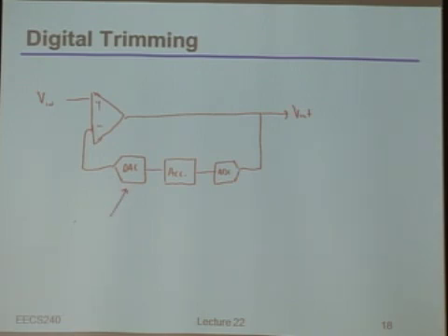So in other words, the LSB or the step size is set by whatever your offset budget is. Because as we'll see in one second, or as perhaps should be obvious, if that DAC has finite resolution, you can never perfectly cancel the offset, right? You can always only get to within basically a step, or maybe half of a step if you're lucky and things happen to be balanced just the right way. And again, we'll see that in more detail in one second.